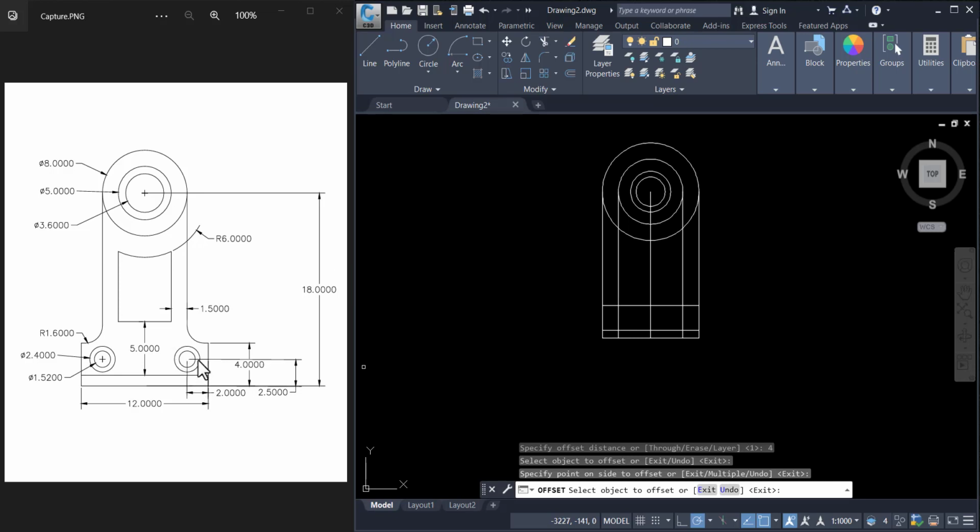We want to offset so that I can draw this circle appropriately from the center point. So I'll offset from this line to this place by 2.5. I'll click the offset tool again, make 2.5, click enter. Escape. You can see that we've actually gotten this particular portion.